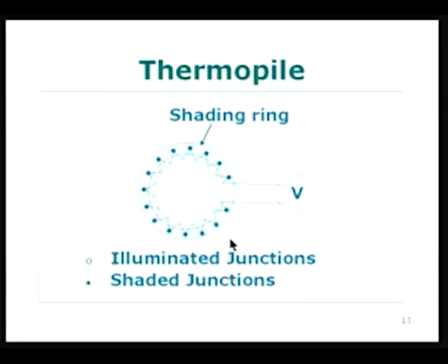In fact, we have also indicated here another use for thermometry. If you remember, we were talking about measurement of temperature and suddenly we have shifted our emphasis. Here I am talking about measurement of solar energy. So, actually the heat flux or the flux from the sun can be directly converted to the increase in the temperature of the junction, and this is proportional to the amount of heat which is falling on it, and therefore, I am able to measure the solar flux using essentially a thermocouple or a thermopile in this case. Thermopile because a large number of thermocouples are in series.